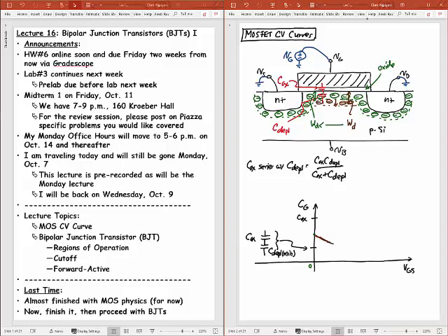And it's going to decrease all the way down to this point here, to the point where I have my minimum depletion capacitance. But right at that point, that's where the channel will invert. Okay, so if my channel inverts, what's going to happen? I guess I'll do that in red here. If that inverts, I'm going to form an inversion layer.